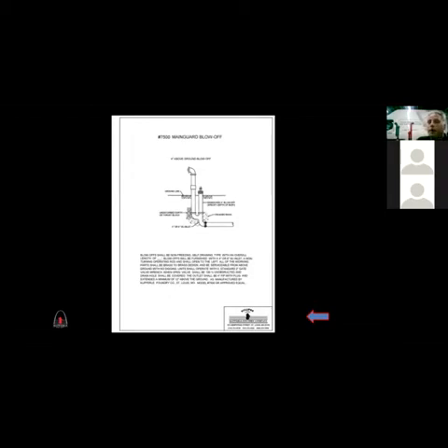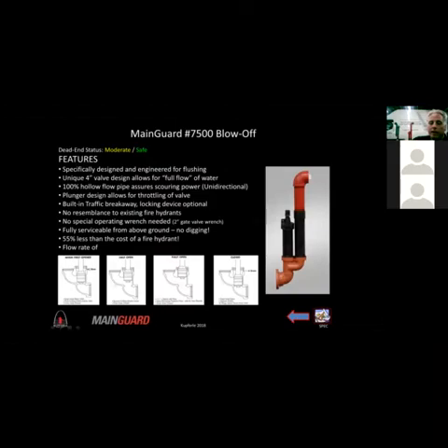So these can do flow rates comparable to fire hydrants at half the cost of a fire hydrant. So if you're looking for something to do a lot of water flushing, for manual flushing like a fire hydrant, the design is better though, because the nice thing about this design again is a valve. When the valve comes up out of the way, the water bypasses the plunger, unlike a fire hydrant. So you don't get a lot of scarring of your seats and your O-rings, and you can usually pass debris up to about 3 1/4 inches out of this one. So you can get a lot of debris out of this particular one.